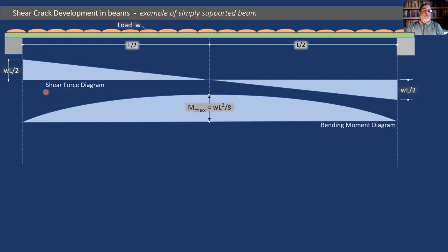it is critical in shear at the supports. So the sections which are critical for bending moment are not critical for shear, whereas the sections which are not critical for bending, where the bending moment is 0, have the shear force at maximum. So while designing, we have to be very careful about which section of the beam we should address for the design calculations.